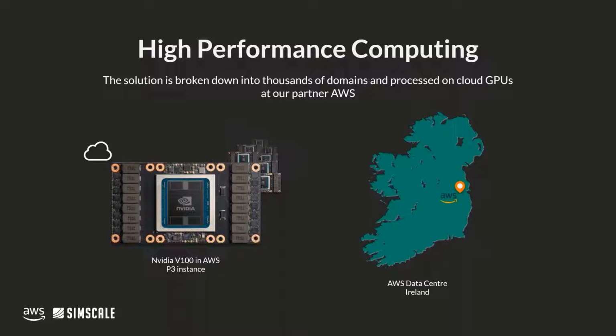Pacefish, an LBM solver written especially for GPU acceleration, connects with AWS GPU instances through the SimScale platform. The Drive AER case of 160 million cells was sent to the cloud, where 8 NVIDIA V100s, each with 5,120 CUDA cores, worked in parallel to push out results in record time.